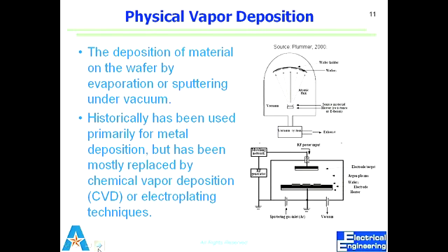Why do we want to do this process under high vacuum? To avoid impurities. All right. What else? For better adhesion. Better adhesion. I don't know why, but maybe. What else? Avoid collisions. Okay, if we avoid collisions, what happens to the travel of atoms? Straight line. What do we call that lack of collision? Increasing mean free path. Right. What is mean free path?